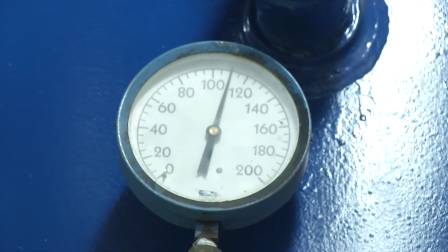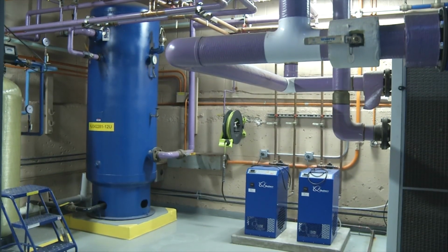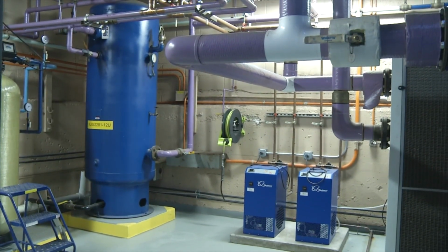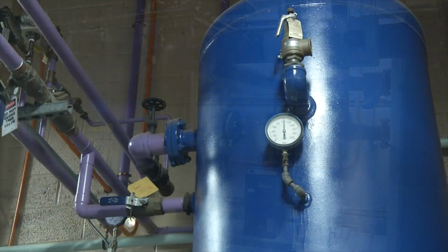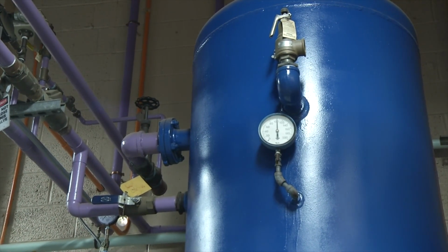smaller type operations, is that you can operate them in an on-off mode. When you reach the desired pressure, you turn the air compressor off using a storage tank to provide compressed air to your facility. When the air in the tank is used up, you start the compressor back up. Terrific, very efficient for the right application.